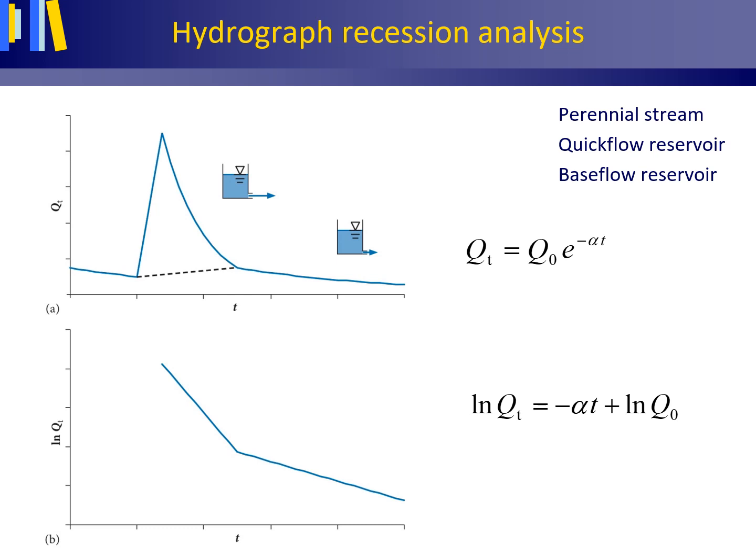The figure shows a base flow separation line obtained using the constant slope inflection point method. The position of the inflection point is found as the point in time where the slope of the semi-logarithmic plot of ln qt versus t changes.